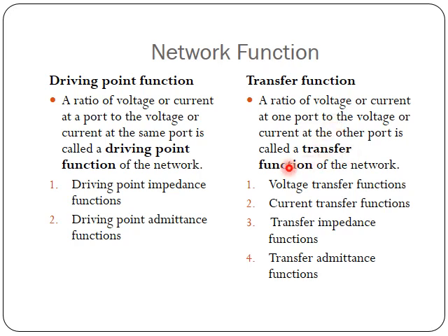Then this is called a transfer function. The various types of driving point function are the driving point impedance function, when it is voltage by current, and admittance, when it is of the form current by voltage. Next, the transfer functions can be of four types.